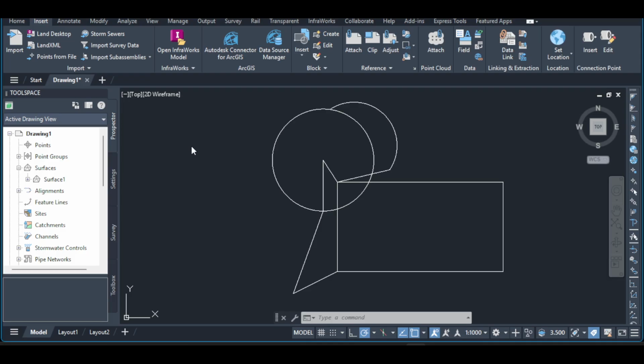Start by opening the Civil 3D drawing where you want to bring in the reference. It's a good idea to make sure your drawing is saved and set to the correct units and coordinate system for your project, because that context determines how the reference will land. If you're working in a coordinated environment, you'll usually want things to come in at the origin with a scale of 1 and no rotation.